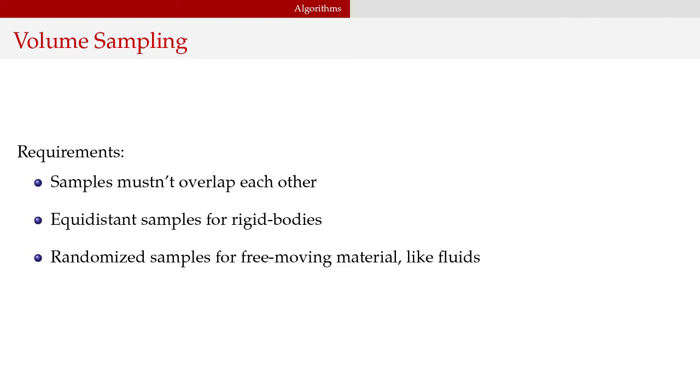If we think of initial positions, it's important that particles don't overlap. When particles in the initial simulation state are squished together, correction forces try to separate them once the simulation starts. Depending on how much the particles overlap, these forces can completely blow up the simulation. But even small overlaps will introduce artifacts.